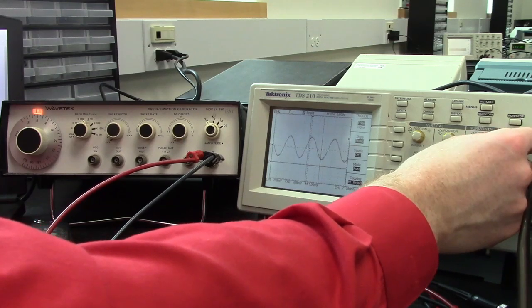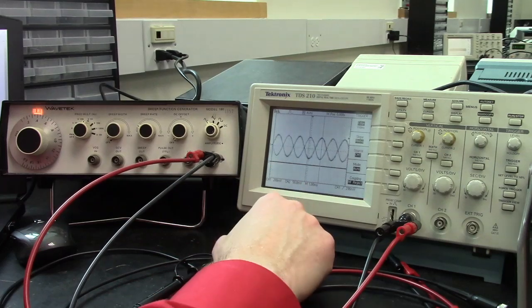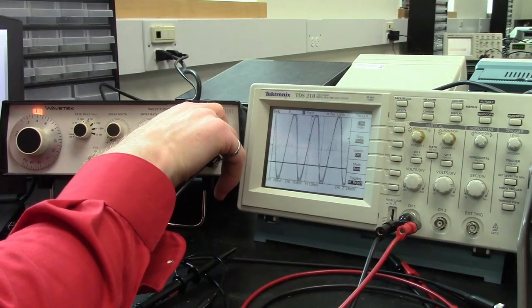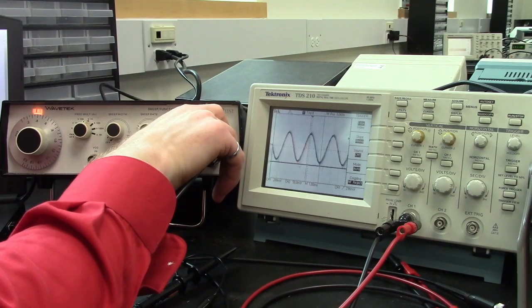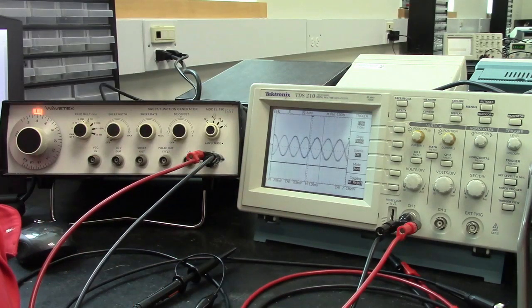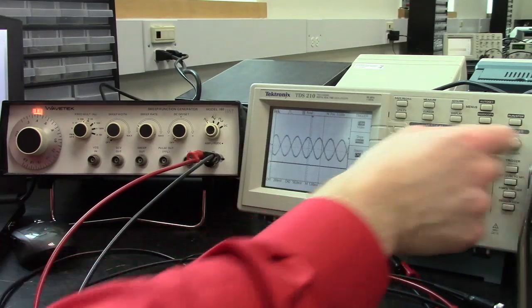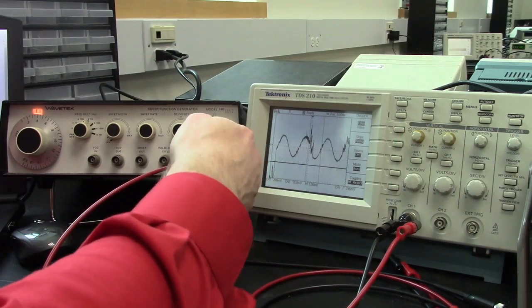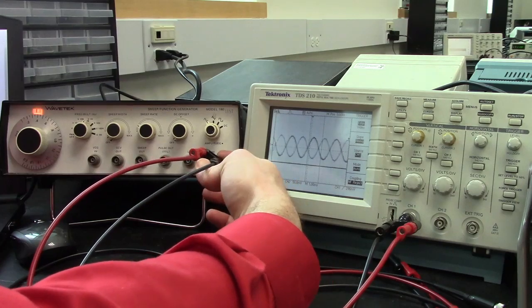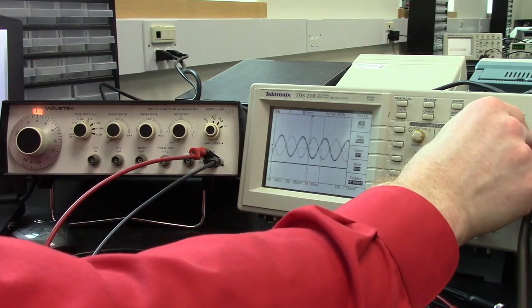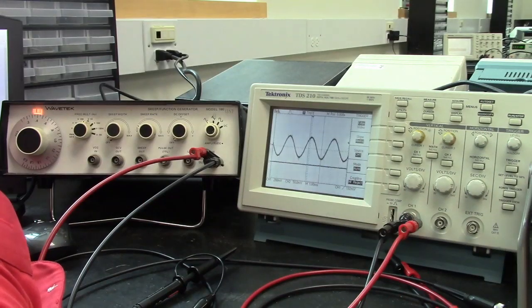So if we go above the level that the signal's actually at, then we can't capture it unless maybe the signal had a higher amplitude, and now we can trigger. But with this lower amplitude here, no trigger detected. So ways to fix that: increase the amplitude, or decrease the threshold for catching a trigger.